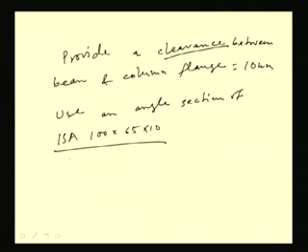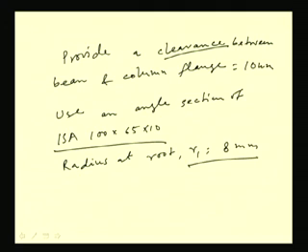That means the radius at root R1, which will be required for calculation, will become 8 mm, and this has been given in the handbook SP6, from which we can find out R1 as 8 mm.